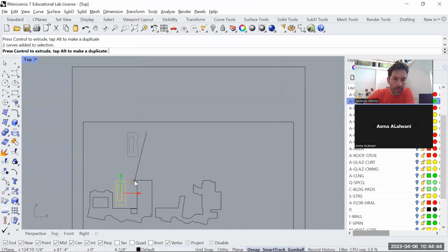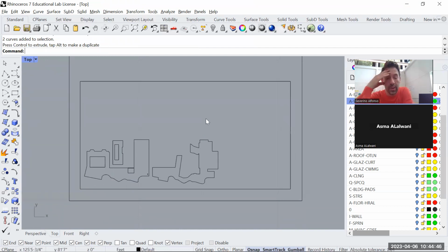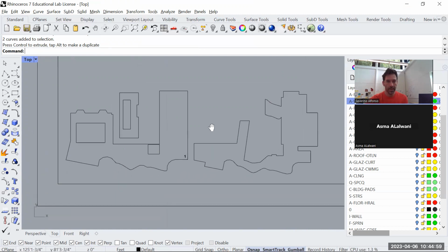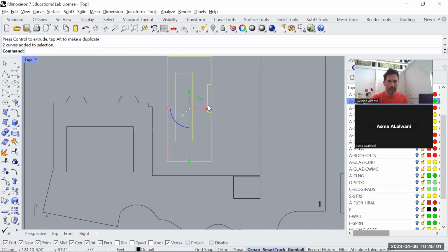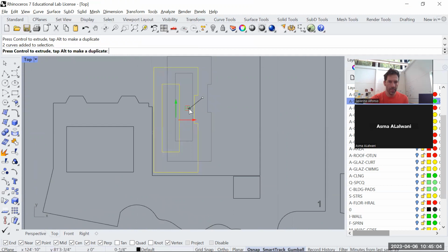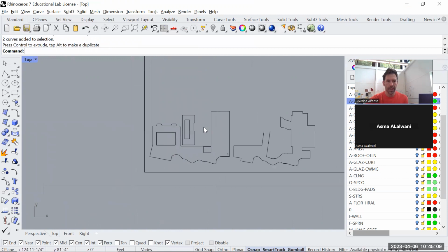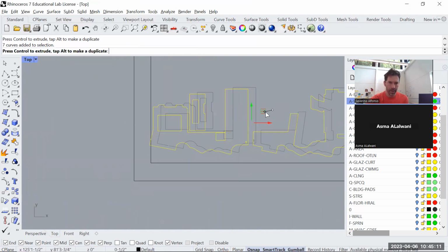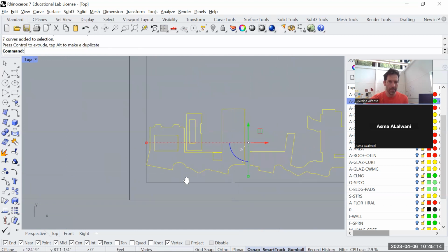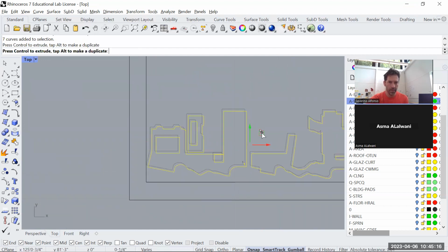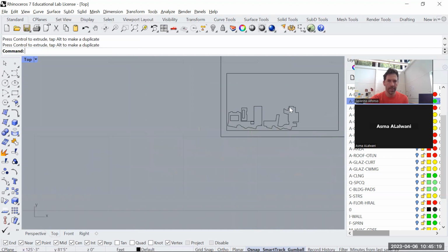In terms of materials, you can also go to the seed lab and ask them, but almost everything goes except plastics, which tend to create fumes and stuff like that. But in terms of woods, you're good to go, and so on. I wouldn't put the piece very close to the other one. Give yourself some space because the laser cut tends to burn a little bit around. I wouldn't put them touching the edge of your material either, because that's not a safe zone. So always bring them with a little offset to the interior. Okay.